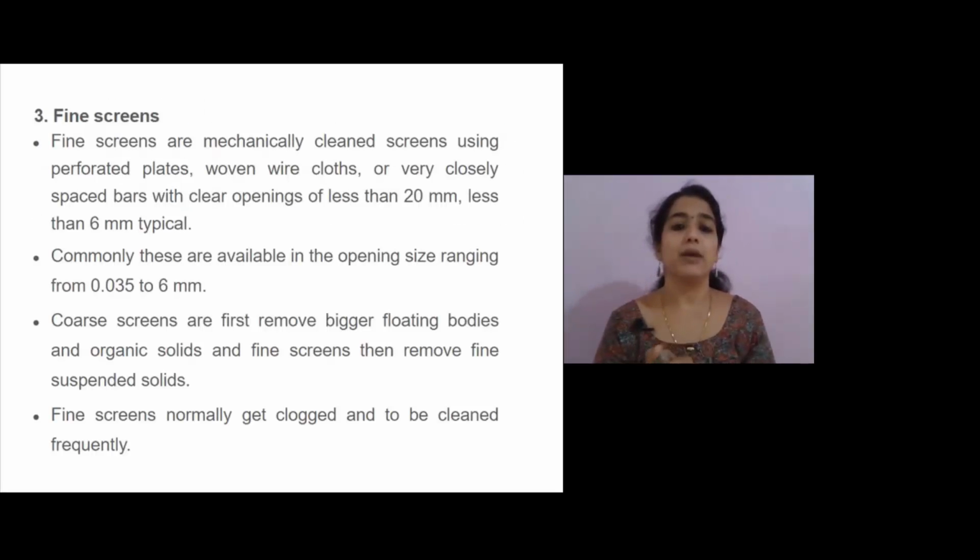Then fine screen. Fine screens are mechanically cleaned screens using perforated plates, wire cloth, or very closely spaced bars with a clear opening of less than 20 mm, less than 6 mm typical. Commonly, these are available in opening sizes ranging from 0.035 to 6 mm. Coarse screens first remove bigger floating bodies and organic solids, and fine screens then remove the finely suspended solids. Fine screens normally get clogged and have to be cleaned frequently.